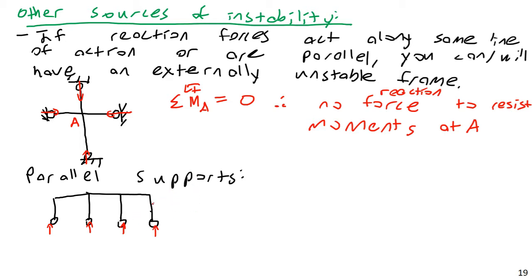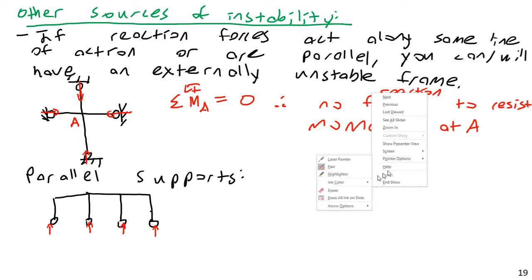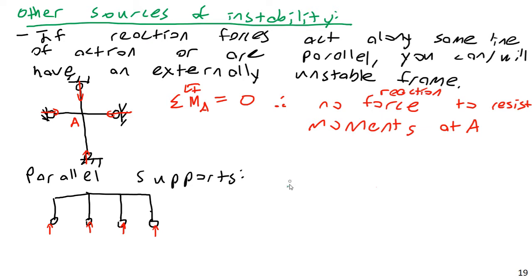But the moment I try to apply a horizontal force to this, it will not be able to resist a horizontal force. So this thing is just gonna roll away. If somebody wants to, they can come along, hitch a truck to this thing, tow it away, and sell it by the pound. So this frame here is good for vertical forces. It's good for moment, but it's not good for horizontal forces.